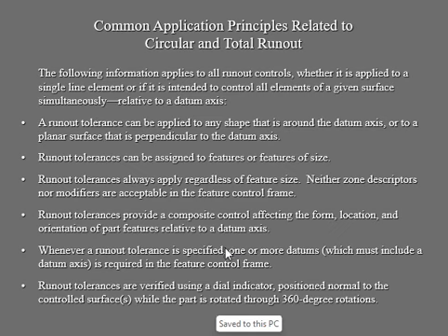Whenever your runout tolerance is specified, one or more datums are going to be required in that feature control frame. When you are reading like this, your brain is not going to connect with the feature control frame, which is your little table identifying what the tolerance is and what we're controlling. Here our control is a runout, followed by the tolerance, followed by your datum. That's always there. The only thing that changes is your control.